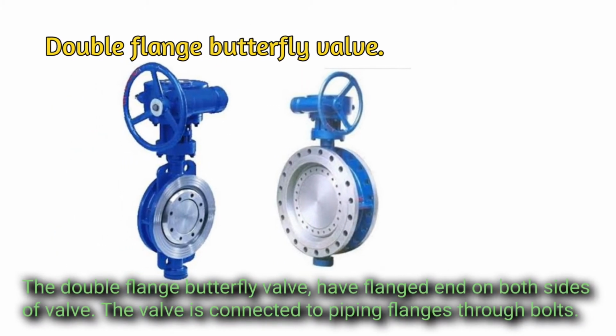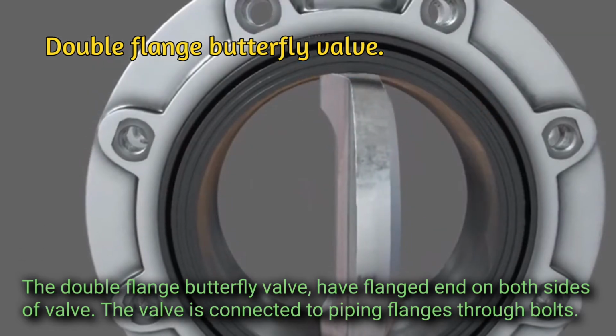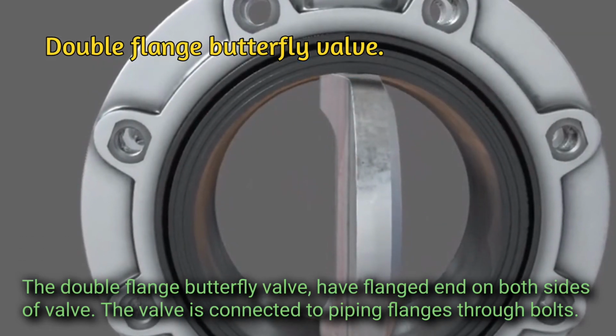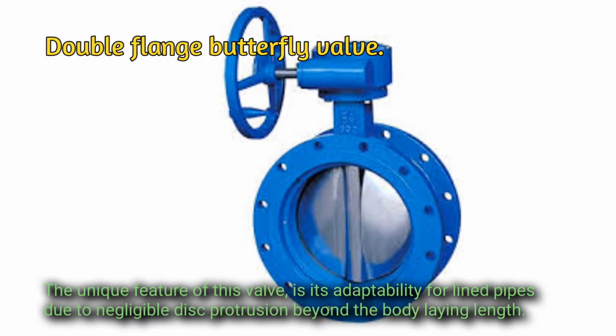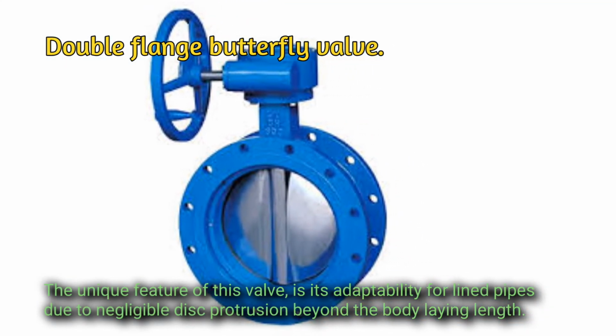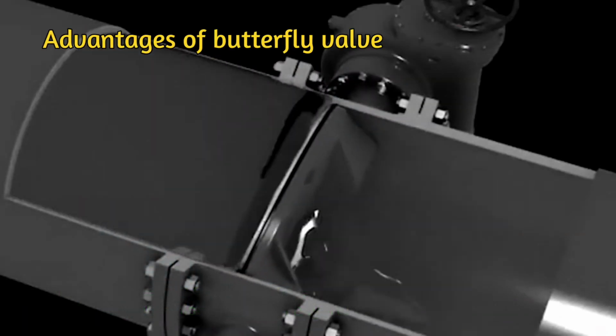Double flange butterfly valve. The double flange butterfly valve has flanged ends on both sides of the valve. The valve is connected to piping flanges through bolts. The unique feature of this valve is its adaptability for lined pipes due to negligible disc protrusion beyond the body laying length. Advantages of butterfly valve.